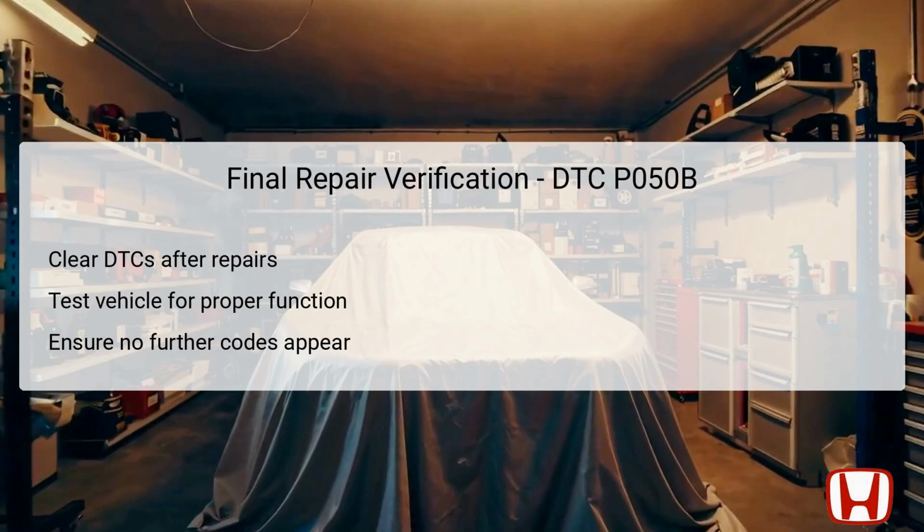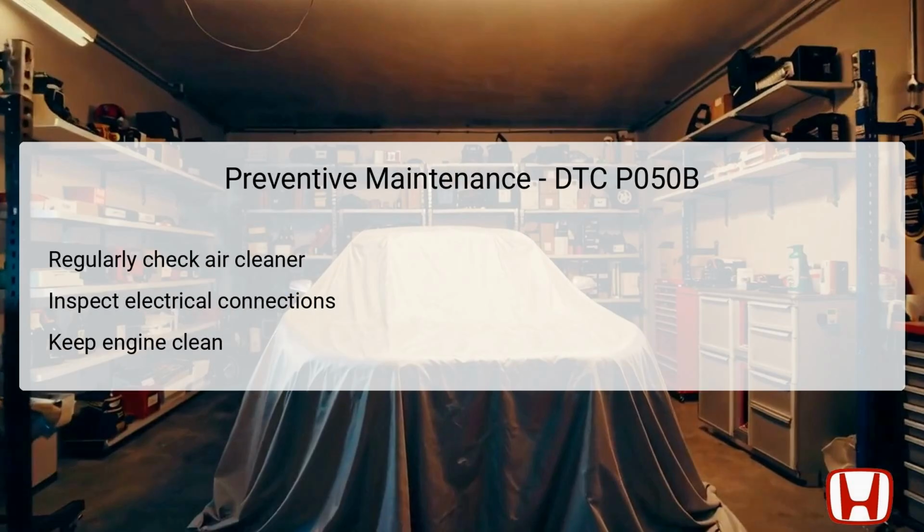To prevent the recurrence of DTC P050B and maintain optimal engine performance, it's essential to implement a consistent preventive maintenance schedule. Start by regularly checking the air cleaner element, ensuring it's clean and free from excessive dirt and debris, which helps maintain proper airflow and protects engine internals.